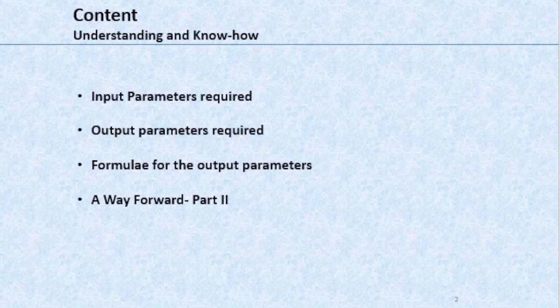The recording parameters are applied to various speed and load points which we consider in line with the ISO 8178 guideline, towards either 8 modes for off-road applications like tractors or earth movers, or 5 modes for stationary applications like power generating sets. The formulation principle has also been considered, showing how cycle level average emission can be derived.